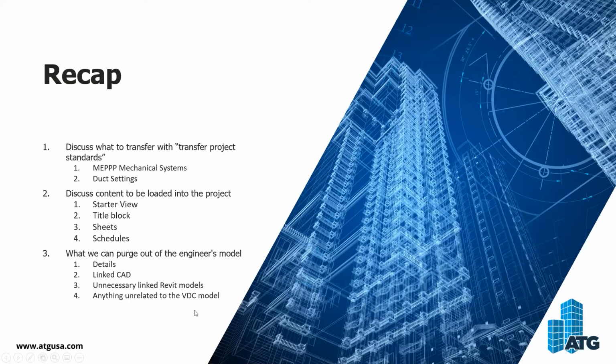So once you get all your view templates added in there, and get your views created, and then you add whatever filters and stuff like that you need, and all your sheets, you can wipe out all of the engineering model stuff that just doesn't pertain to you guys.